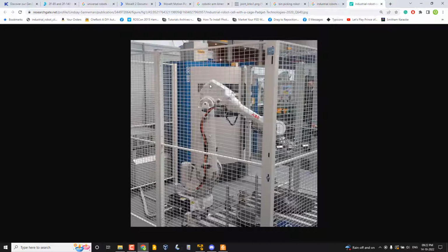I mean, if the robot is hitting a human, for example, it can't detect the collision. We can detect the collision maybe using some cameras or something, but by default there is no provision to detect it. So if there is a collision with some human inside the cage, then we need to immediately press the e-stop button, the emergency stop button. Otherwise, even fatalities can happen.